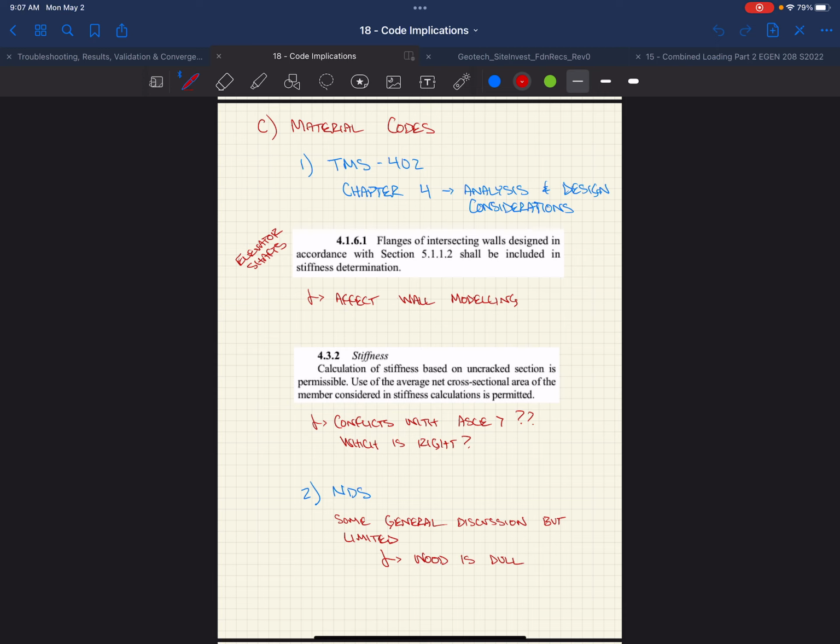The reason why they do this is that it has to be a hinge, right? If you ever see a brace frame where the gusset plate looks something like this, it's 9 times out of 10 a special brace frame, okay? When we were touring the health center across the way, none of them looked like this. They all did this, right? And that does not allow for a nice rotational hinge of that gusset plate, okay?